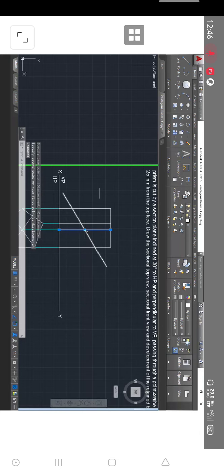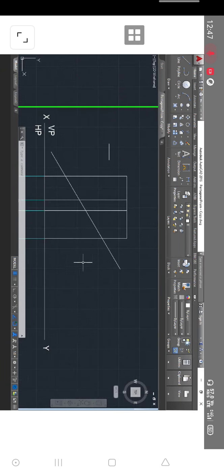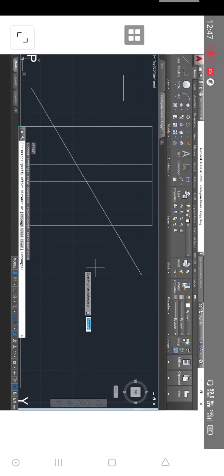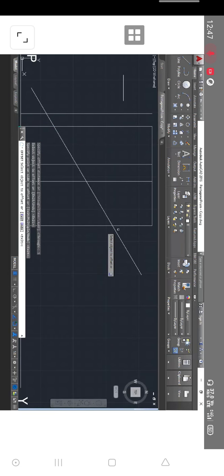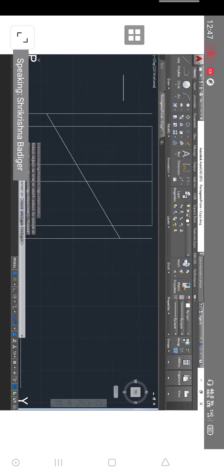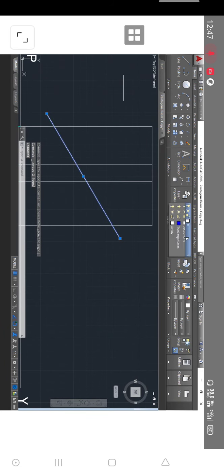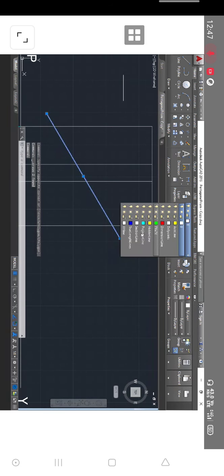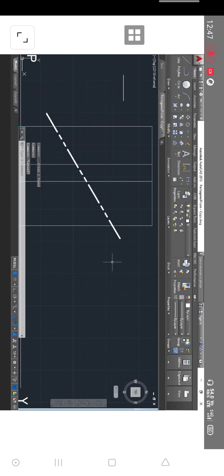Now, for you, what you are doing manually is you just mark it with pencil, and you know the point. In AutoCAD it doesn't happen that way. I'm going to offset these lines by 5 to trim this section plane line. So this is our section plane. And there is a section line. This is a section plane.